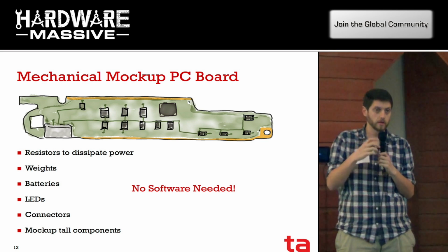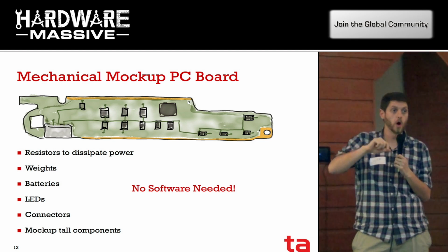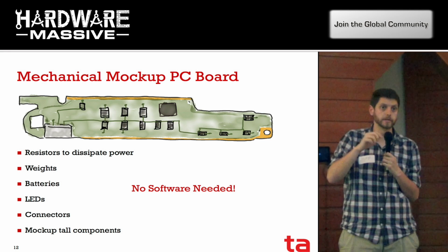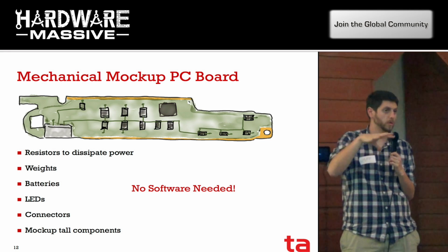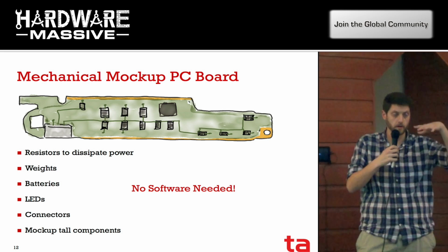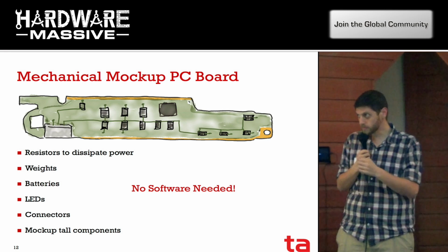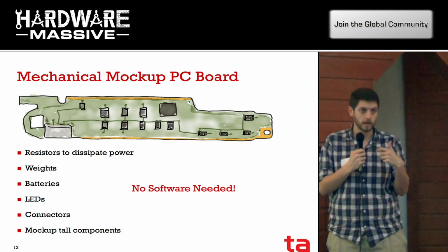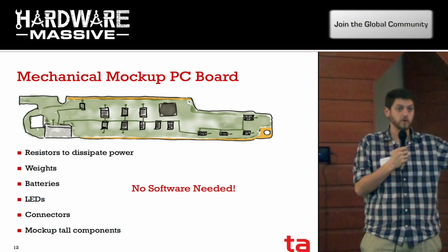And further, I think that maybe the only live components that are really crucial to add are the ones that you know are going to be very tall, whether it's big electrolytic caps or various other components that have a potential to interfere with other parts of the mechanical side of the process. If you do this, oftentimes your mechanical engineer will be very appreciative insofar as you don't have unwelcome surprises late in the process where the integration test comes in.